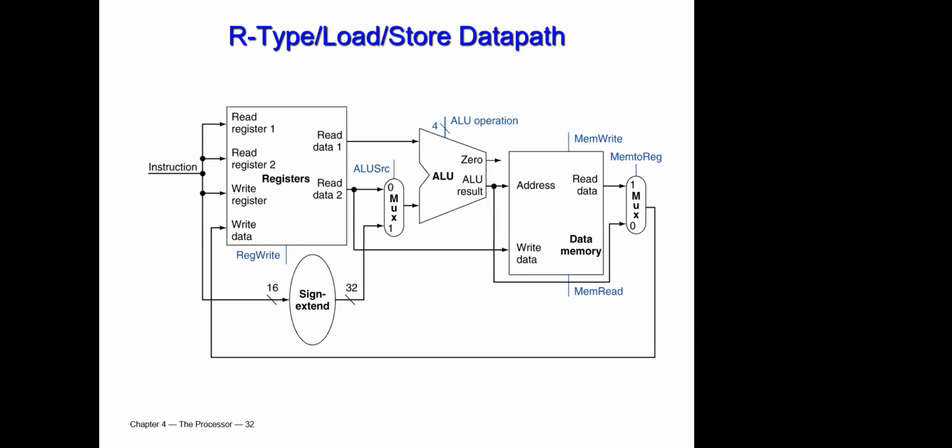This is exactly what we will do. We have to calculate that address. How? Again, take my base address and add it to my offset. I now know exactly where I should write. Now I have to have a pipe that physically will take the data that is inside my register and copy it to my memory. That's why I have to have that particular connection physically, correct?